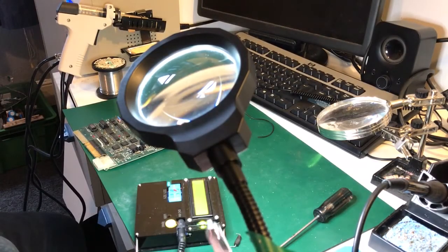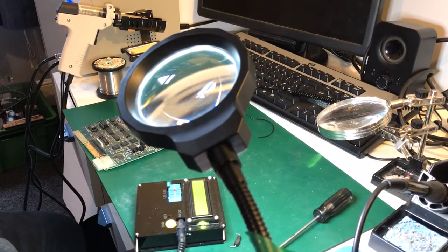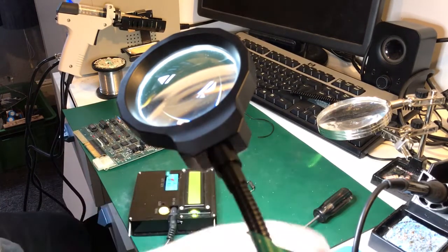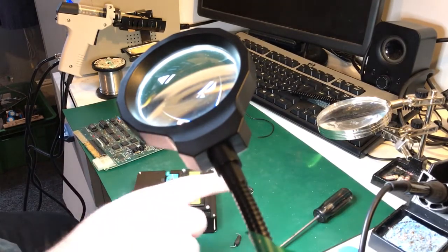Okay, 50 nanofarad. So it looks like both of those, even though they look a bit charred, are actually working ones. And they both have the same V-loss reading of 0.2, so I'm suspecting they're okay. So we put them back in, and we'll find a replacement capacitor for these two, and check the actual values. I'm going to suspect they're similar capacitors.